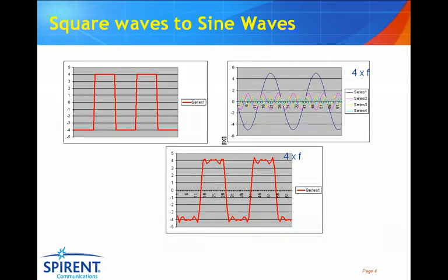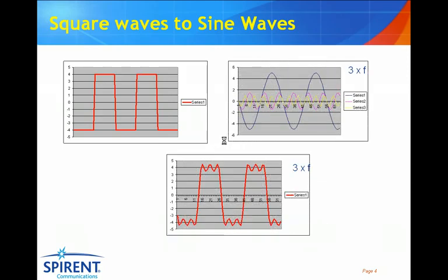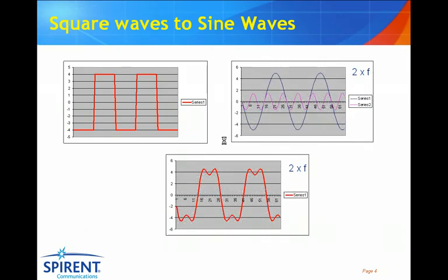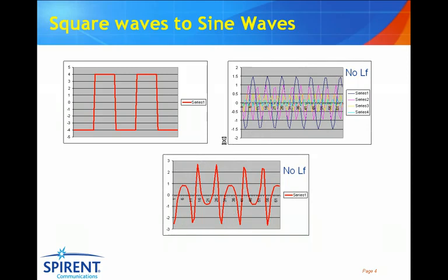You can see below we still have an approximation of the square wave, but it's got a little bit more softer or raggedy. If we take out more information, the picture becomes effectively softer and softer. However, if we take out the low frequency component, we're going to lose basically all coherence in the picture. Like so. So although we've got all the high frequency components, because I've removed the low frequency, we've really lost the square wave completely. And this is very much analogous to what's going on within the MPEG algorithm.